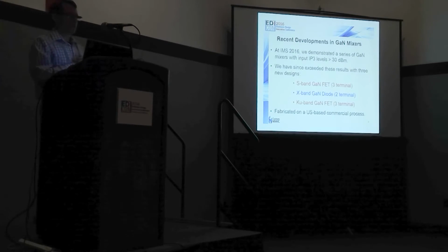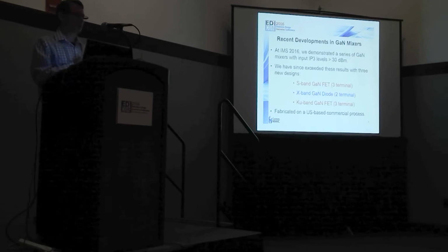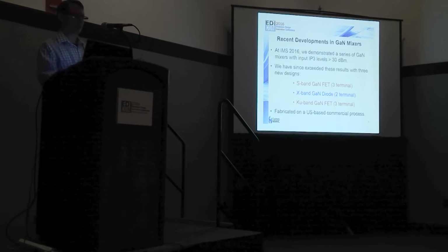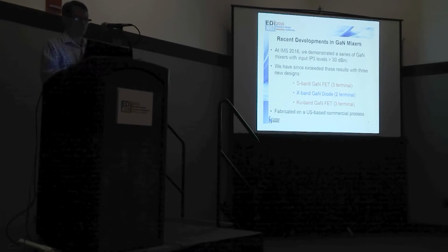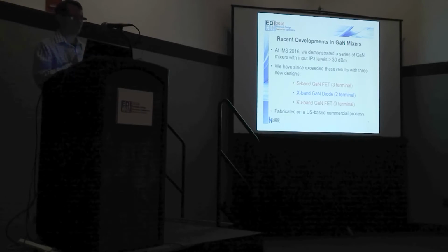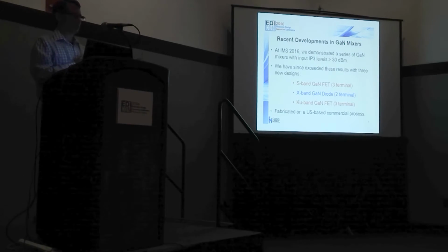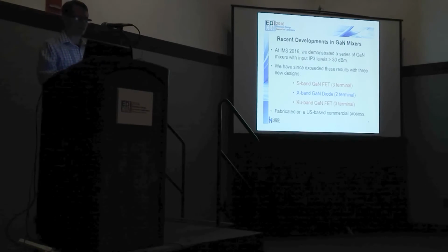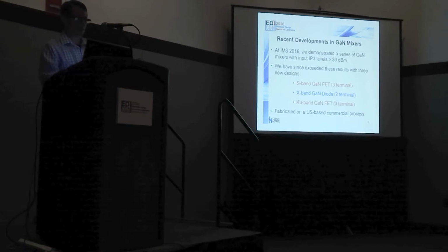So a few months ago, back at the IMS in San Francisco, I was fortunate to give a micro lab on some of the GaN mixers we've done at Custom MMIC, and that was really our second generation GaN mixers, where we got input IP3 levels around 30 to 33 dBm pretty consistently. I'm happy to say that what we'll be looking at here today is our third generation set of designs, and we've really exceeded that IP3 level by quite a bit.